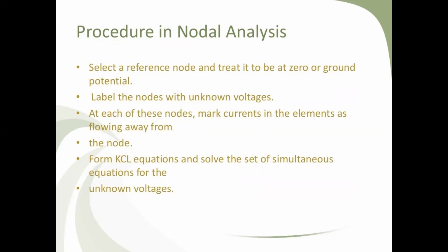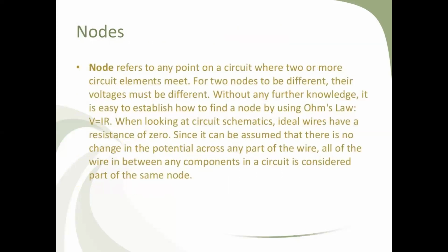At each of these nodes, mark currents in the elements as flowing away from the node. Current passing from one node to another should be noted. Form KCL equations and solve the set of simultaneous equations for the unknown voltages. We have to apply Kirchhoff's current law to form the equations and then solve them.